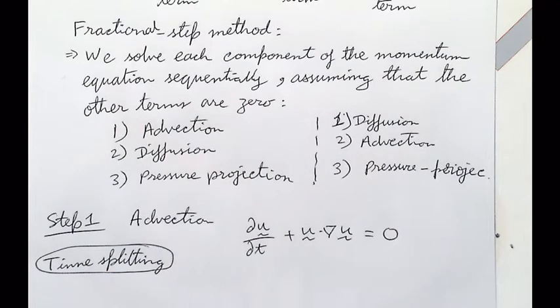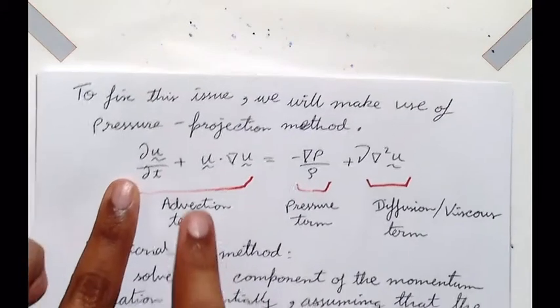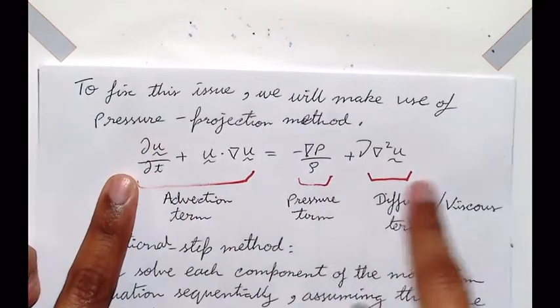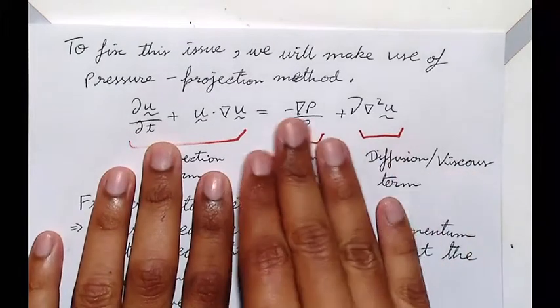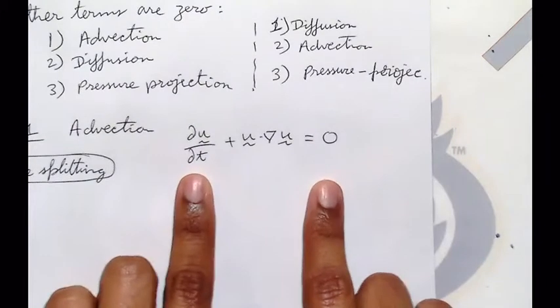Mathematically, we are putting everything to zero, right? That's how we solve the Navier-Stokes equation. The three terms, we equal them to zero. So see, we have, this is no assumptions, full Navier-Stokes. The first thing we do is we only take the advection terms, others can go to zero. That is exactly what we have done here.